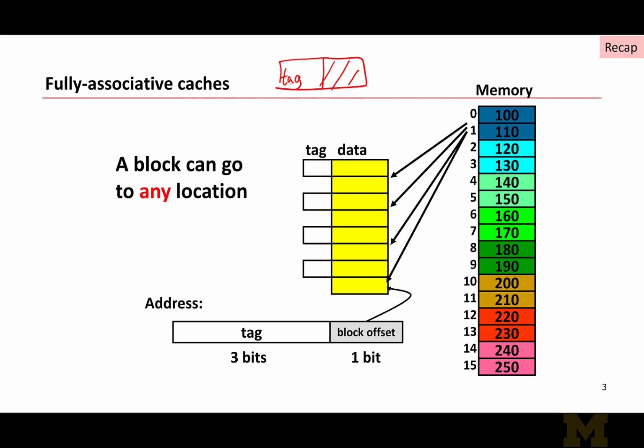And so therefore the cache overhead was prohibitive. The way we solved this problem was by increasing the size of the data that is stored per tag. We called this the cache block. And so now you need to have only 1 tag per cache block as opposed to 1 tag per byte. And that significantly reduced the tag overhead.